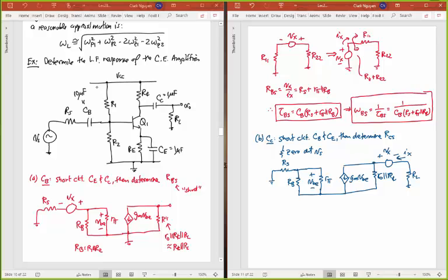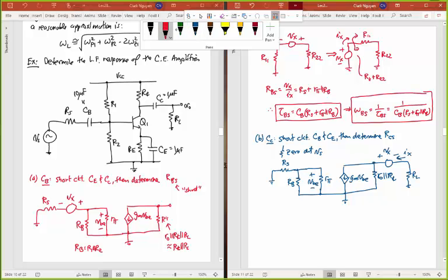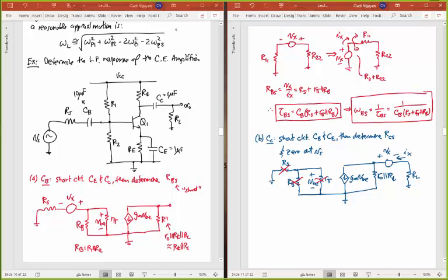Okay, but I have the same thing again. I have a voltage source here between two resistors. All this is going to ground, by the way. If that's going to ground, then I have no voltage across any of these resistors back here. So as far as I'm concerned, these resistors aren't here. The VBE goes to 0, so that also is nothing. And so all I really have in this circuit are just these two resistors here. And I've got that voltage between those two resistors. That's exactly the same situation up here.